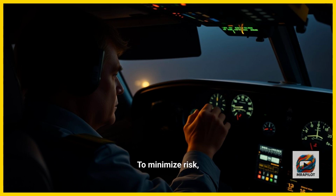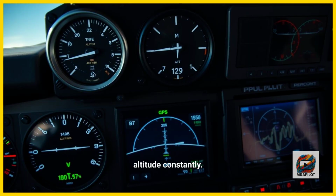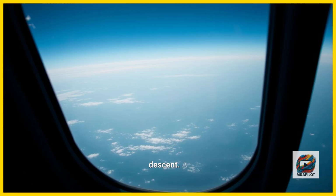To minimize risk, pilots must cross-check altitude constantly. Compare altimeter readings with flight director, autopilot, and GPS data. Also, verify level-offs during climb and descent. A 200-foot deviation at FL 350 may seem small, but it's a serious issue in RVSM.